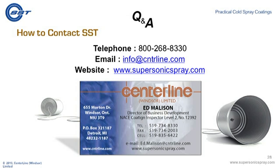Can you cold spray stellite cobalt-based material? Stellite cobalt-based material is a very, very hard material, and the rule of thumb in general is the harder the material, the lower deposition efficiencies we achieve. Now, with the Series EP that we mentioned earlier in our presentation, we do have some abilities to spray harder materials. I think at this stage it's a little bit of a stretch for us to consider a straight stellite cobalt application with relatively good performance. I'm talking now about actual production performance parameters. I'd certainly like to talk to the customer more about specific application, but I'm thinking just off the top of my head that may still fall into the thermal spray category, Mark. Okay. Okay.